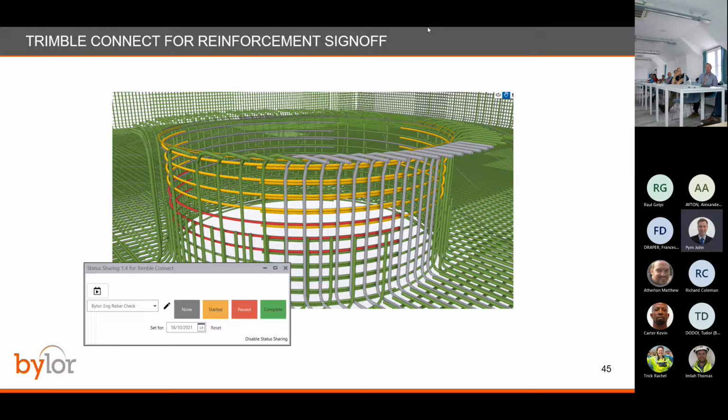The fantastic thing about doing all of this digitally is obviously that gives you data that you can then work with. So one of the experiments we did was, instead of using the digital model to try and highlight bars to get their mass, or maybe having a really poorly organized spreadsheet, what we want to know is how many tons are we installing a week for productivity purposes, so we can adjust our program so that we can plan to have the right amount of labor.